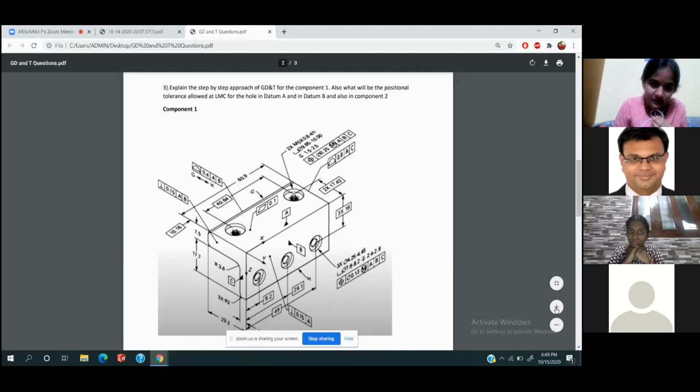Okay, good. When you're going towards LMC, the maximum is 10. Sorry, when you're going to LMC, the value will be 10. So now explain to me from 9.65 to 10, how you are taking this 0.25. 0.25 is the position tolerance, right? Yes, sir.